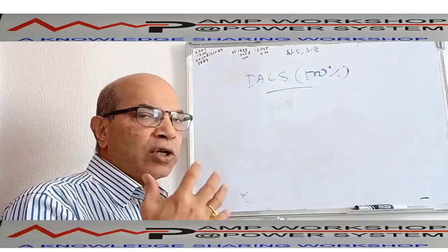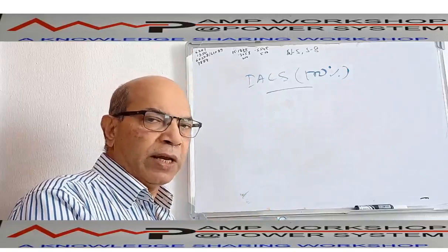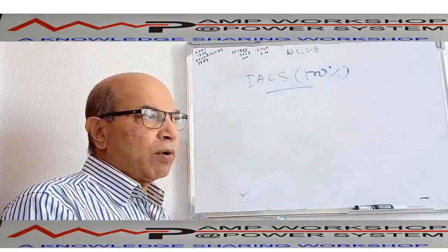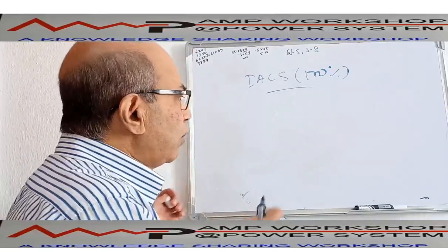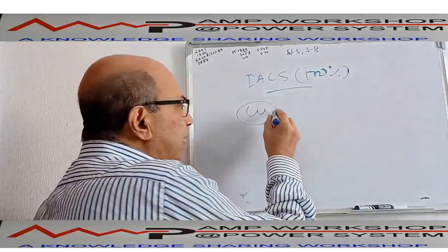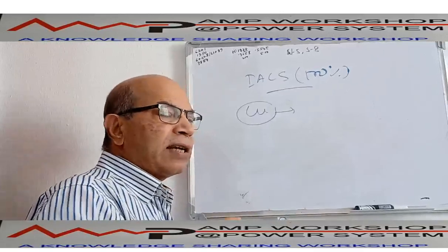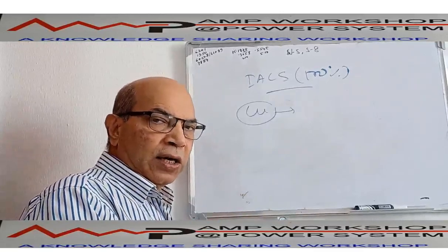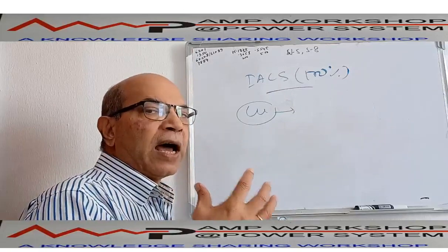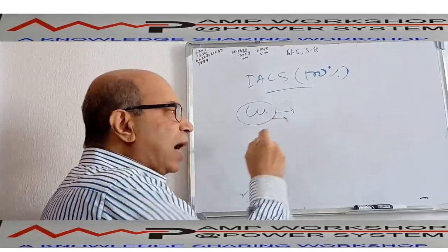Then it should be corrosion resistant. If the overhead line goes through a corrosive area, corrosion should not be severe. Considering all these points, copper has 100% conductivity as per the IACS table, and it has good mechanical strength. Another point: there is an I²R t heating loss in the conductor, so the conductor should have low resistivity and high conductivity. Copper has a very low resistivity, which means it has a high conductivity.